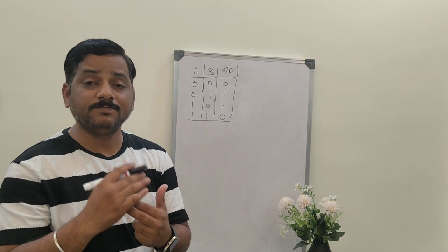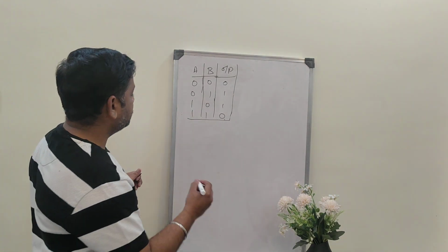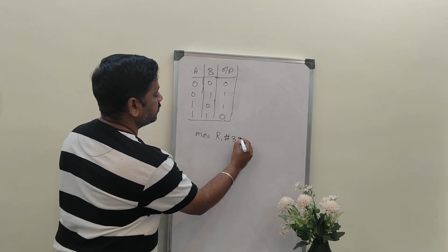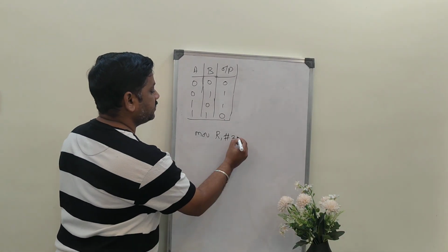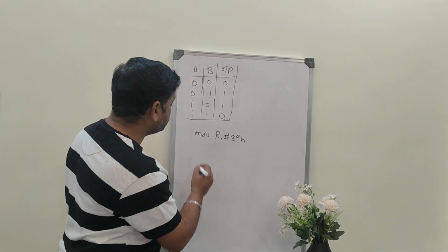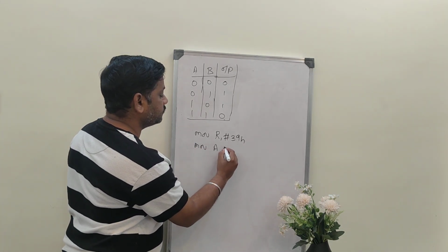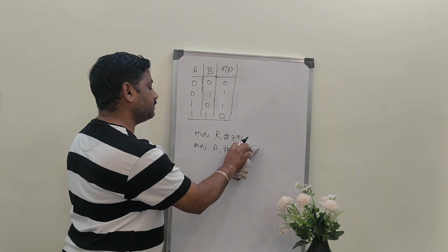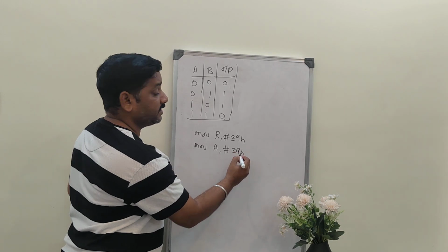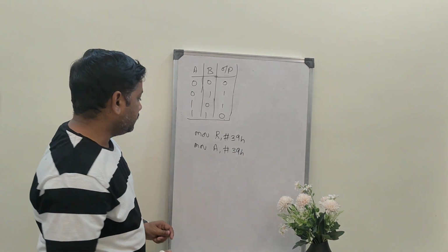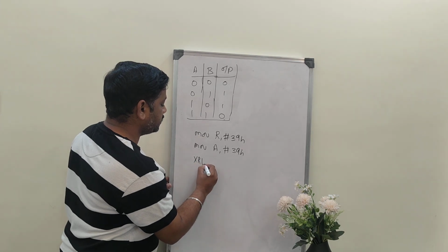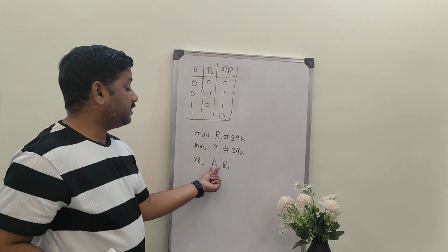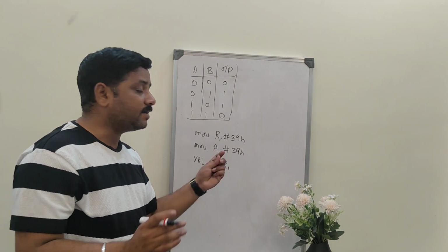First, let us take inputs in the accumulator and register 1. I will take MOV R1, #39H. One number I have given, and then I will take another input for the accumulator, MOV A, like #37H. Or let me take the same number here and tell you what's going to happen in the XOR gate, #39H. Now what I do is write XRL A, R1. Now the content of A and the content of R1 will be compared together.